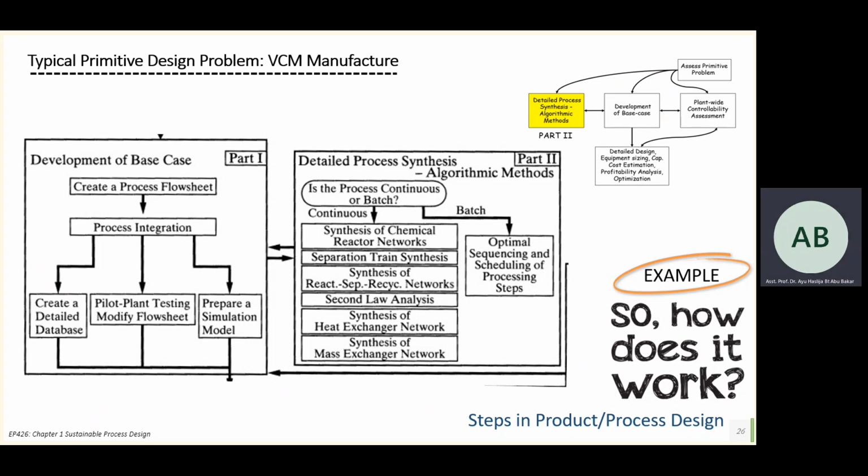Okay, then after that, create a detailed database. What are the databases that you require? Okay, pilot plant testing, modify the flow sheet, prepare a simulation model. UniSim or ANSYS Fluent, any suitable software. Okay. Then once you come up with the base case, only then you go for detailed process synthesis.